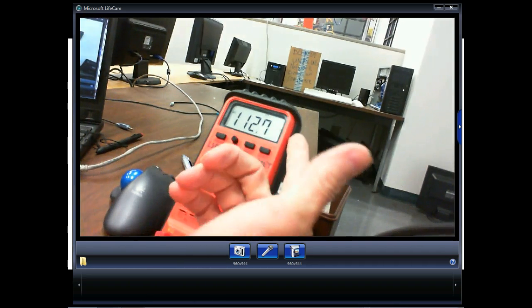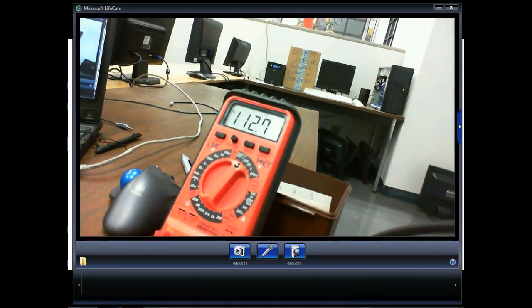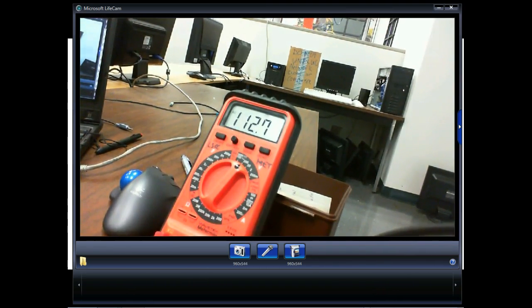So when you put your meter on AC, it's not measuring peak, it's not measuring DC effective voltage, it's measuring RMS. And so if we say 120 volts AC, it's assumed you're talking about RMS, because the meters don't measure peak, they don't measure peak to peak, they measure RMS.